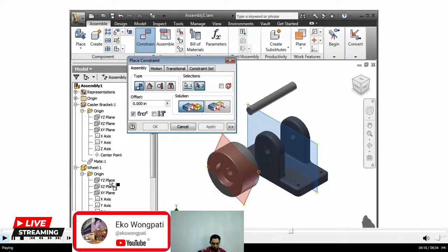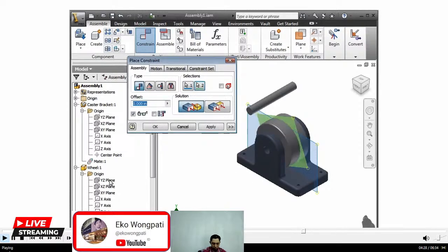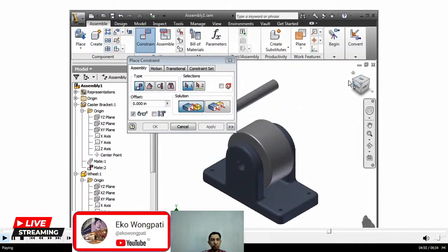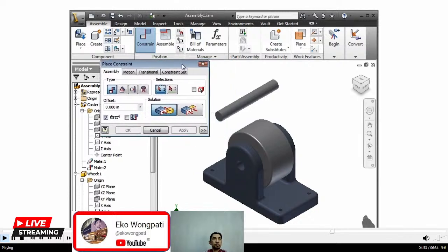As you become more experienced, you'll find that you'll be thinking ahead as you design parts to have the reference planes end up in places where they help you at the assembly level like we have here. As soon as I select the other plane, it snaps into place. Notice they highlight in colors that correspond to the color of the selection buttons. If I again look straight on with the assembly, you can see it's centered within the bracket. Because of the design intent we incorporated with this approach, if any components get wider in the future, they would still remain centered here. At this point, all I have to do is insert the pin.